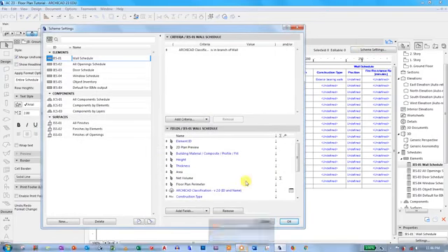going to help me to come up with a proper costing for this wall. And so what I should do is go back to my Archicad, and then I can filter the fields that I want to include, and just save the information that I require. Then I go back to Excel, open that, and I can start working on the costing for the wall. So let's go back to Archicad, and I'll click on scheme settings, and I'll remove this. I'll remove from here, and I'll remove the positioning, fire resistance, all these properties, because I don't want to use them.